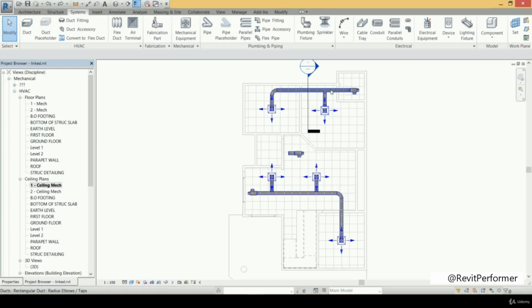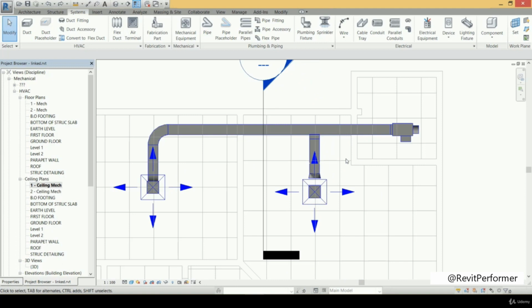And the insulation of any duct has two types, the interior insulation and the exterior insulation. So the exterior insulation is used to insulate the inside air, or the supplying air that is going inside the ducts. We need to insulate it from the outside or the surrounding temperature of the outside air or the outside climate. And this is because the inside airflow is the conditioned air.